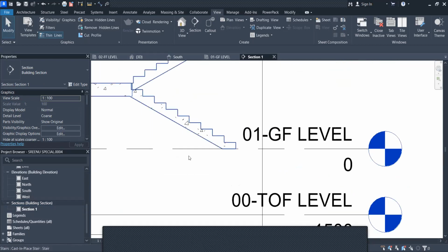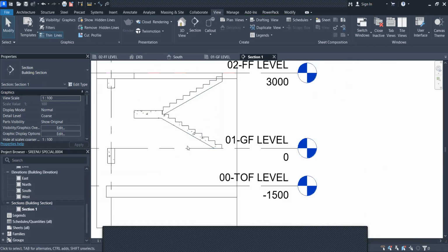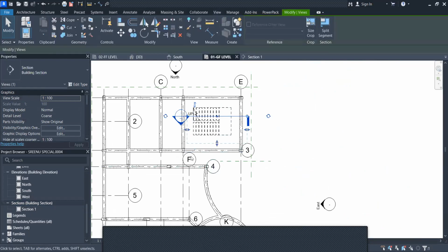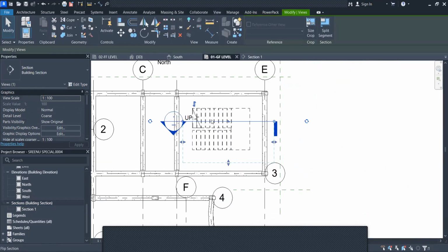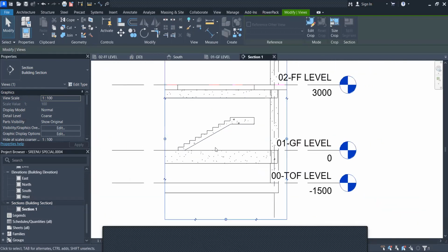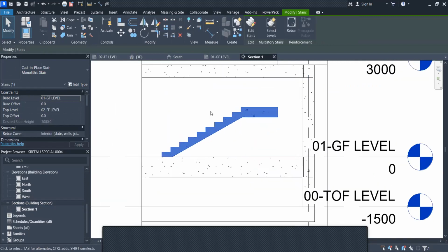All right, so you just need to select on this one. Okay, now let me first of all go back there. Let me flip it on the other side so that I just start with 1. Then go back here so that I just have 1 for now. So that we start with this one. So I'll select on the stair from here. Now for this one, we are going to use stair reinforcement by sketch.